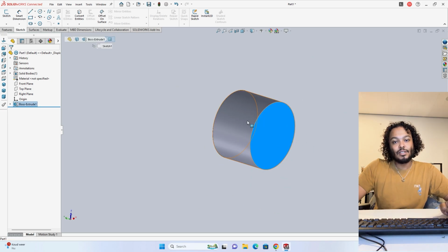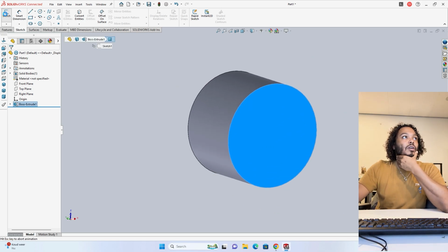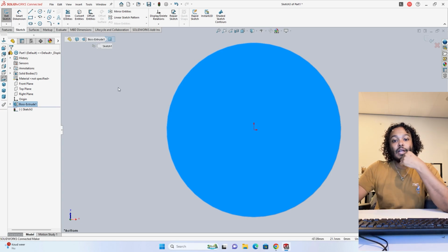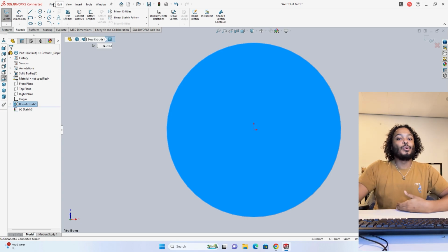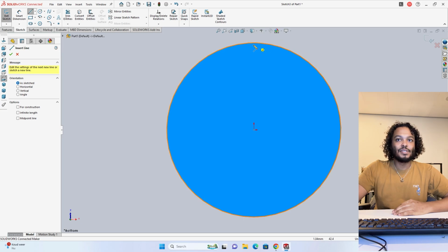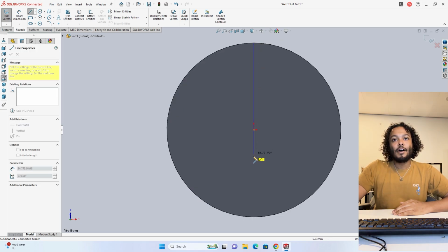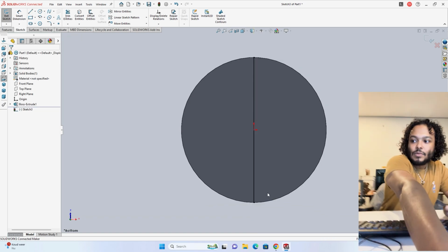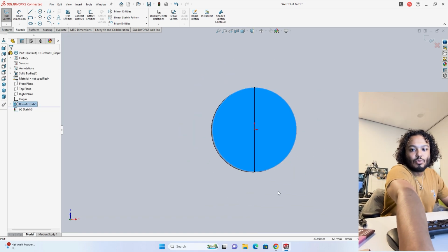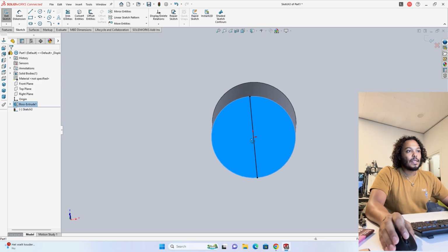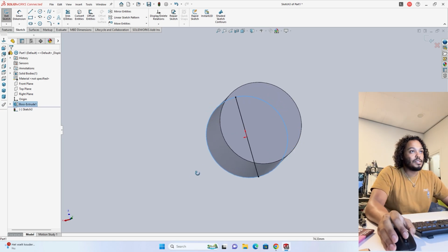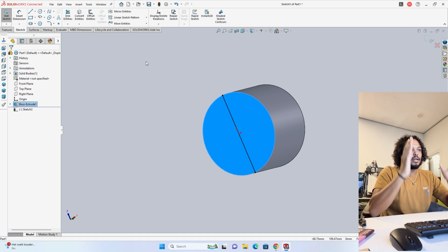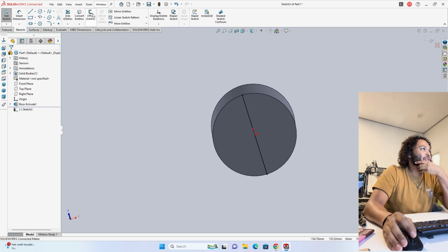As soon as you select a flat surface in SolidWorks, you can press the sketch tool again, and then we'll use that surface to sketch upon to create your next design feature. In this case, I want to draw a line that goes from the top to the bottom. I'm going to place my camera a little bit more like this, and that is basically what's going to allow us to then also cut off the end caps.